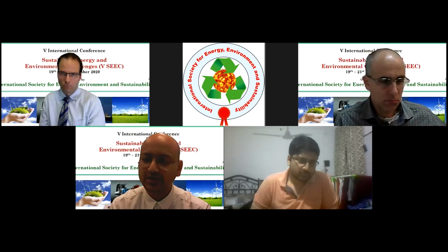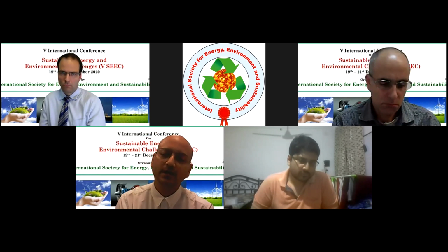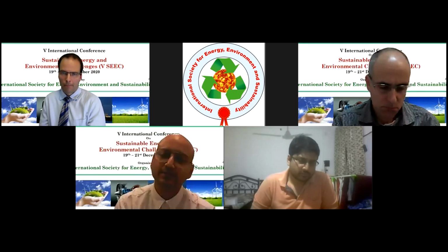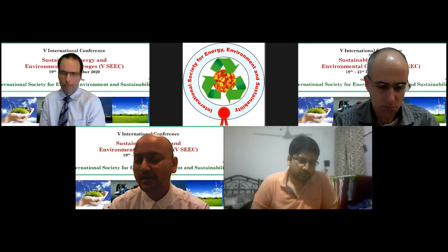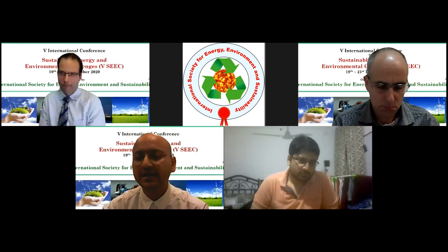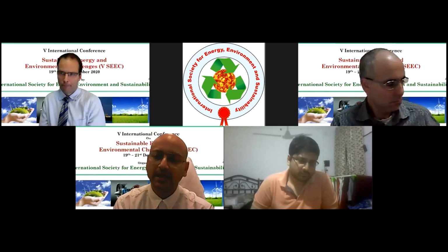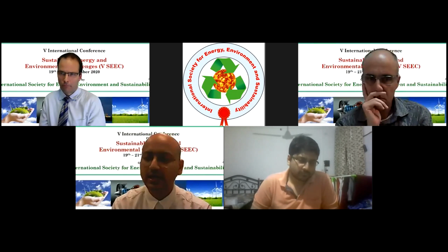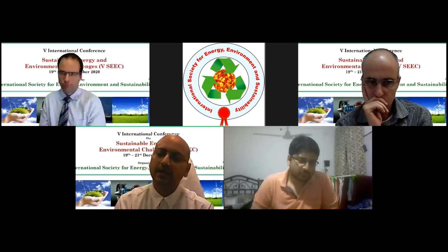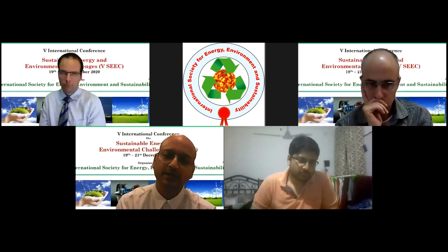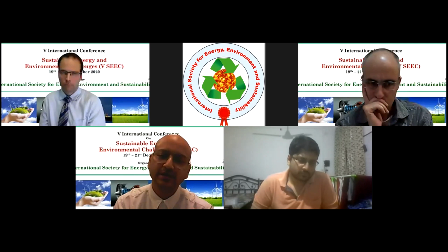So that's one issue: what kind of input water we are getting. And if you are talking about some remote places in India, and some places in Rajasthan where we have really high TDS water that is not treated, then obviously we can go for this kind of RO system. In terms of economics, it all depends on the quality of input water you have.